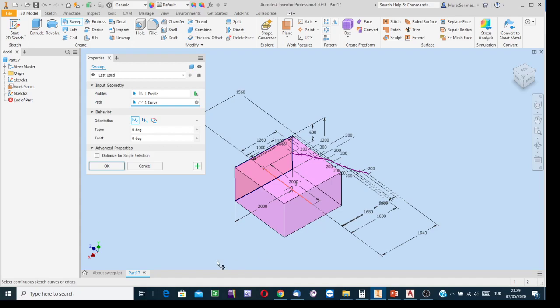Actually, if my purpose were rectangular prism creation, then I would apply the extrusion process. The trick is that if the sweep is to change its cross section from the inlet to exit, such an object, whose cross section is changing in size, is called a loft.